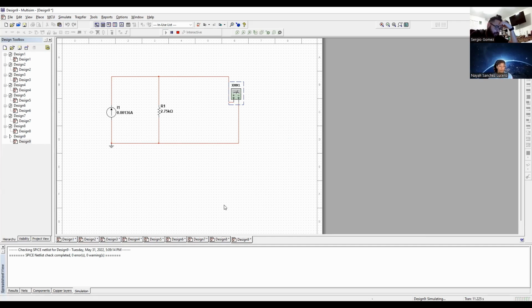Interestingly enough, whether we had the resistance value for R3 equal to 1 kilo ohm or 2 kilo ohms, and this is where we come into our conclusion, they end up effectively being the same theoretical circuit, which is interesting because you would assume that having that resistance value be different would cause a very large impact to the circuit. But it seems as if, due to the nature of the circuit, what only really matters is what's on the left-hand side of the circuit, and that resistor value doesn't have a very large impact on the overall circuit.